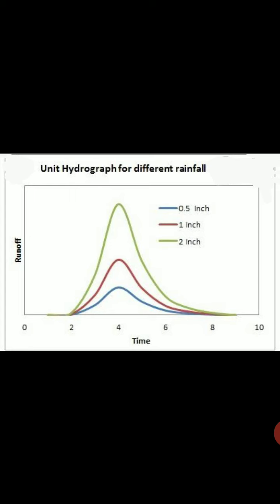The effective rainfall or rainfall excess is the part of the total rainfall that enters the stream as direct runoff. The specified or unit duration is that period within which the effective rainfall is considered to be uniformly distributed. A unit hydrograph is designated according to the unit duration.